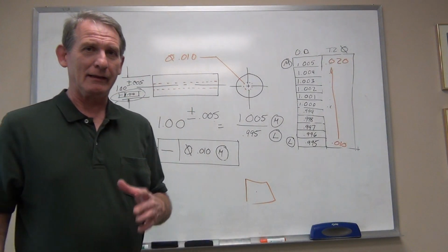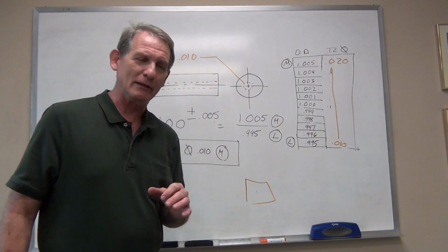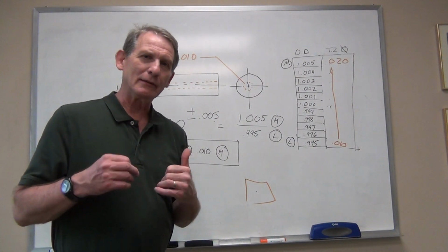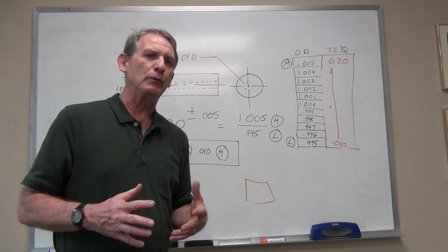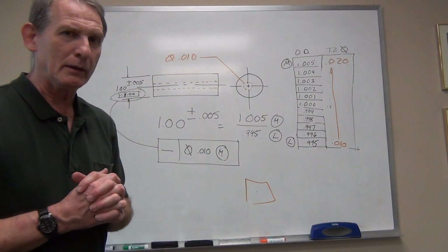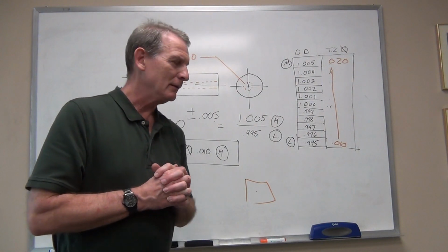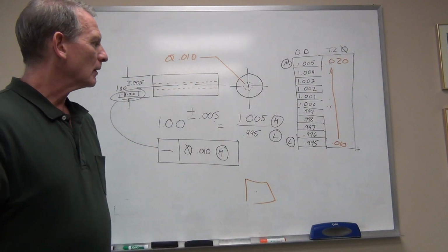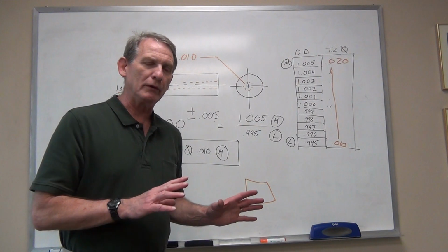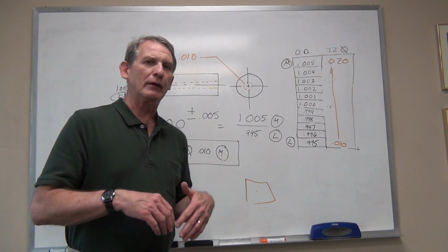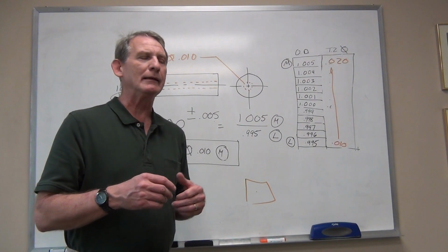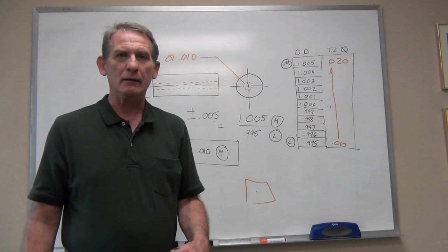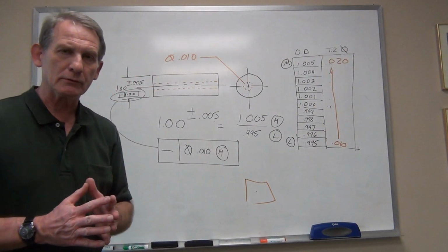if you're not careful. And then again, that carefulness is something that has to be trained into engineers. You don't just say, oh, I'm going to go ahead and do it because I can, because it does adjust the tolerance zone, and you can end up with some pretty bad parts being accepted based on not thinking through what all that additional tolerance is doing to your parts. Okay, so let's leave it at that. I want you to review this. Make sure as we go along that you're thinking in terms of what is the adjustment to the tolerance zone based on the limits that are established by the dimensions.